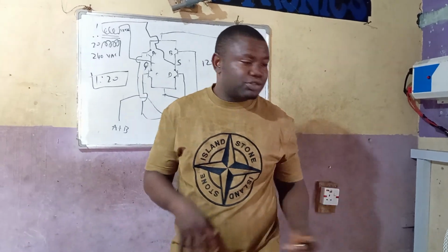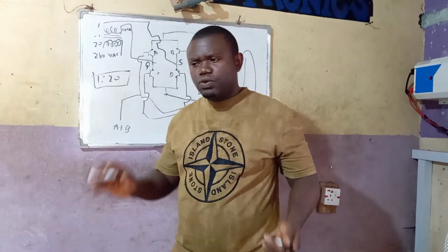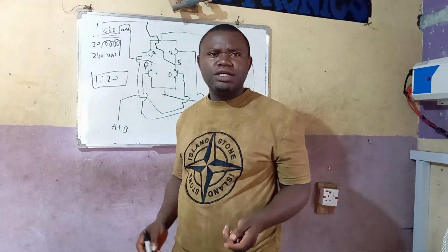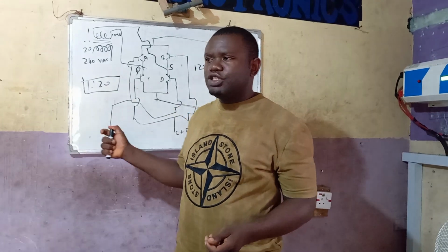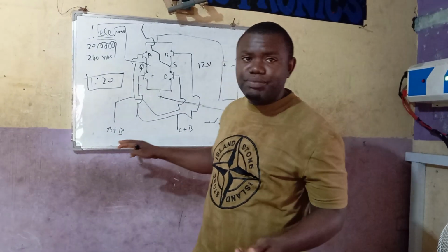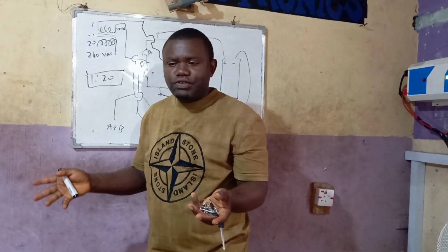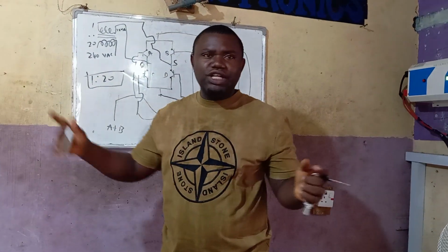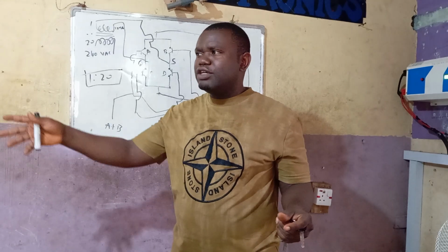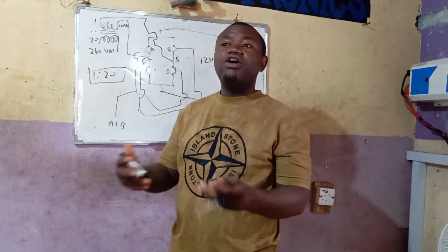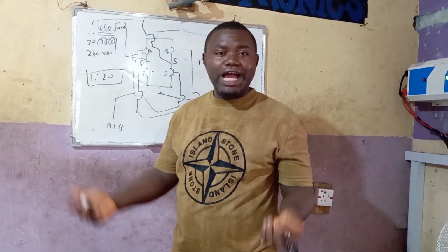It helps your electronics work better, your fridge works better, your fan works better. This one is more like a square wave system because of the IC that is switching it. SG3524, 3525, and many other ICs like that, 4047 and so on, are all square wave ICs.